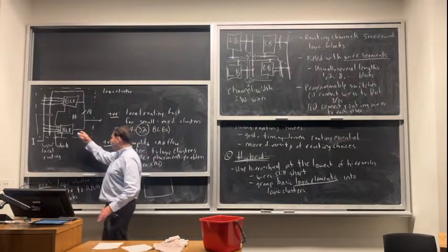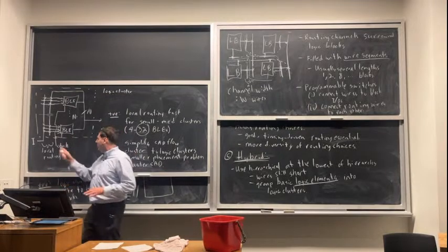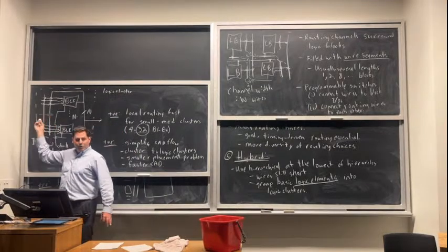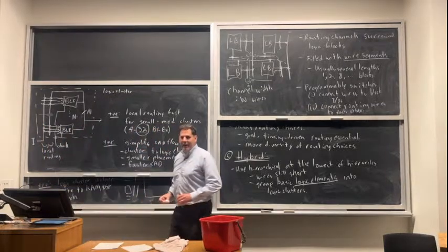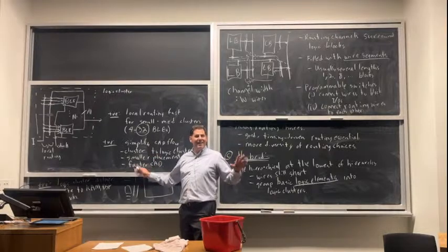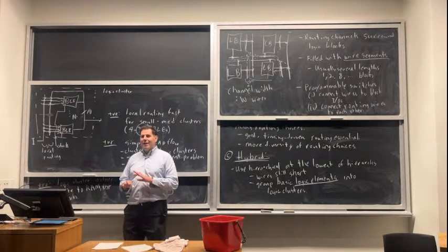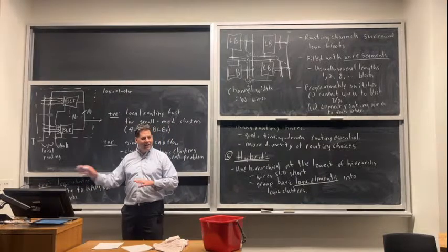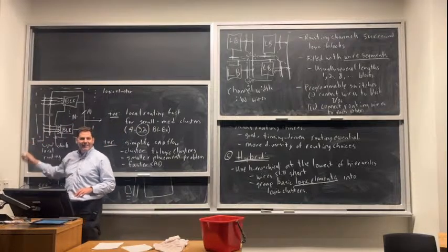Altera, which for many years has used this, said that at 10 and 7 nanometers, they see some problems. So they started putting in these shorter wires that kind of make it two levels of hierarchy. And Xilinx basically said at 10 nanometers, this is out of control. This island-style FPGA is too big, takes too long to route, and we got to stop so many signals from going out to the regular island-style routing, so we need to have bigger logic clusters, and we need to have more local routing. So it's actually kind of interesting.